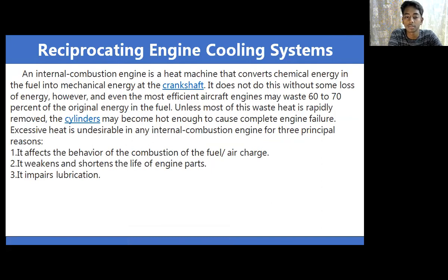Reciprocating engine cooling systems. An internal combustion engine is a heat machine that converts chemical energy in the fuel into mechanical energy at the crankshaft. It does not do this without some loss of energy. Even the most efficient aircraft engines may waste 60 to 70% of the original energy in the fuel. Unless most of this waste heat is rapidly removed, the cylinders may become hot enough to cause complete engine failure, as we discussed earlier. Excessive heat is undesirable in any internal combustion engine for 3 principal reasons.